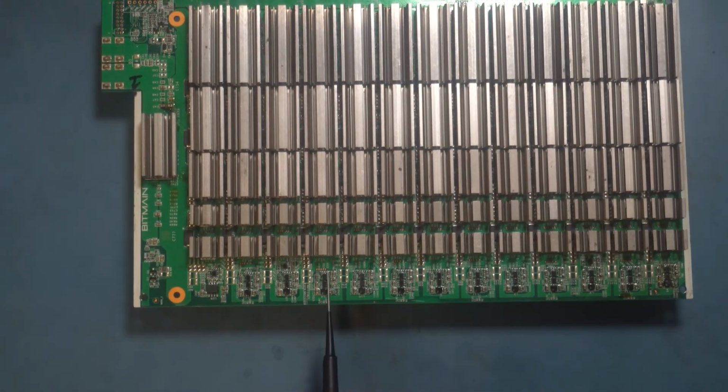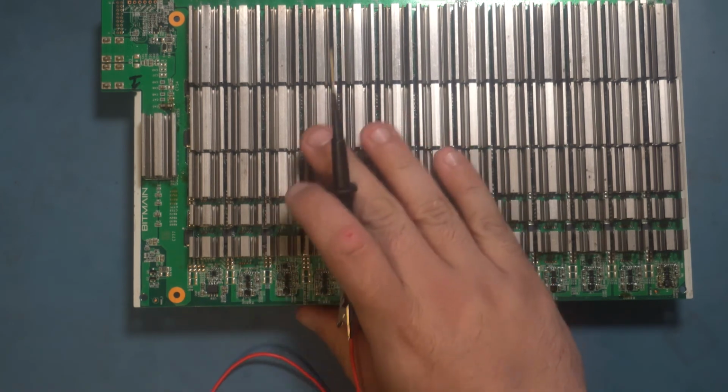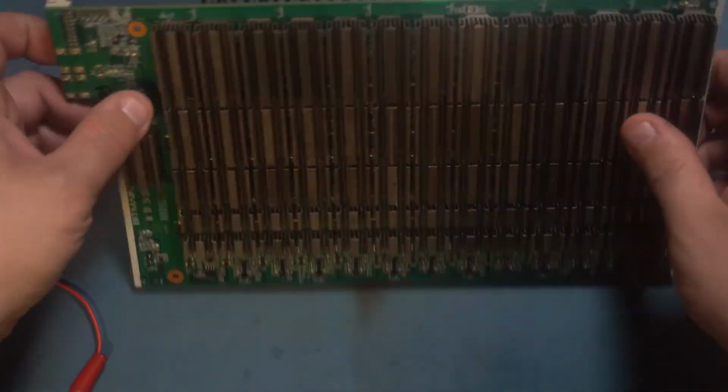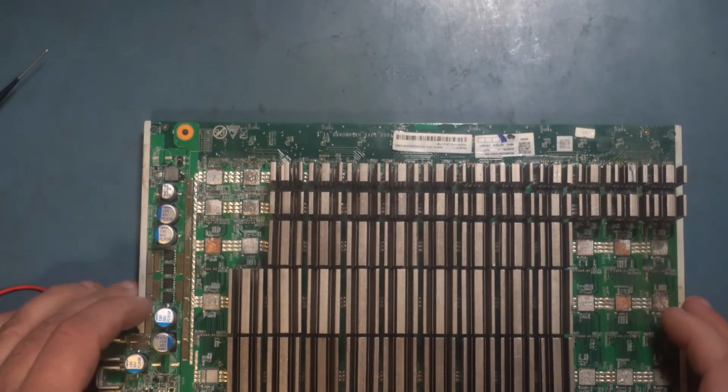So it comes to a point where, depending on how the board is designed, you just don't have enough headroom on your board voltage to use enough voltage as an input to your LDO to generate a strong 1.8 volt. So that is where your boost circuit comes into play.